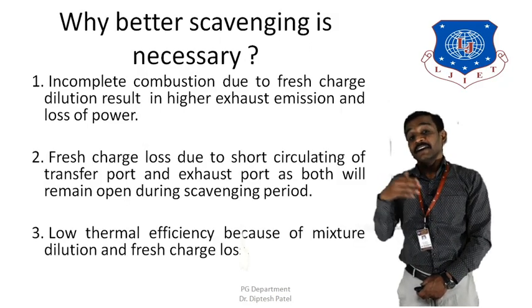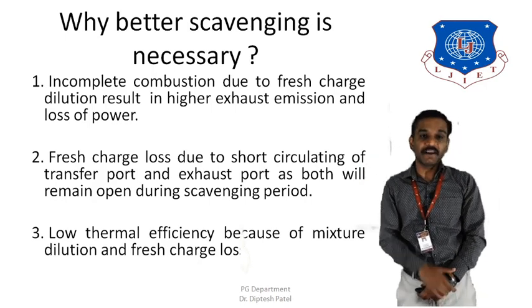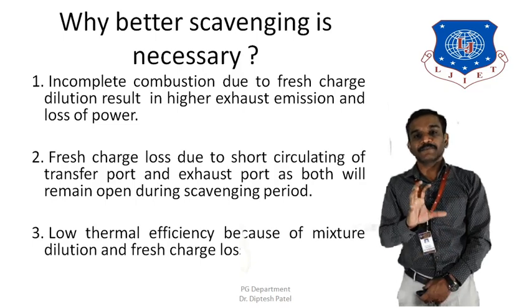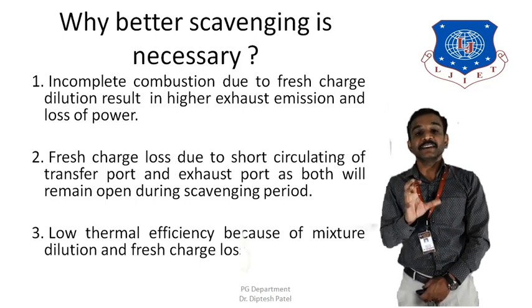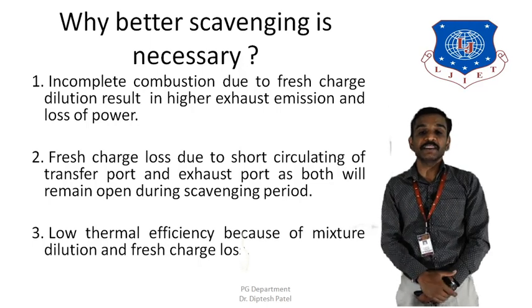Now why is it important to have this scavenging process? Why is it necessary? Since we know that there are a few incomplete combustion gases, they would dilute the fresh charge if they are not completely removed from the engine cylinder.